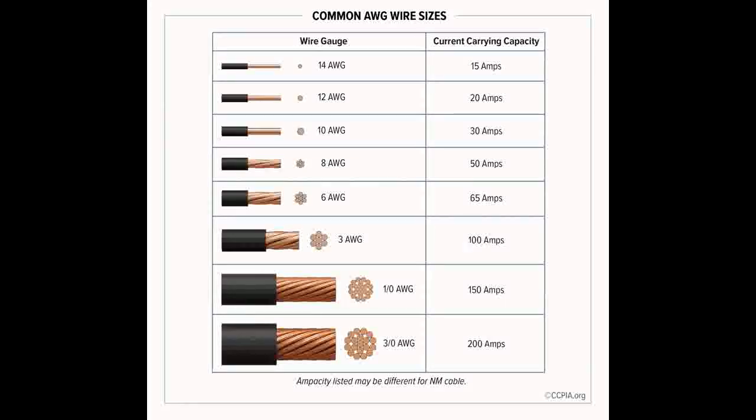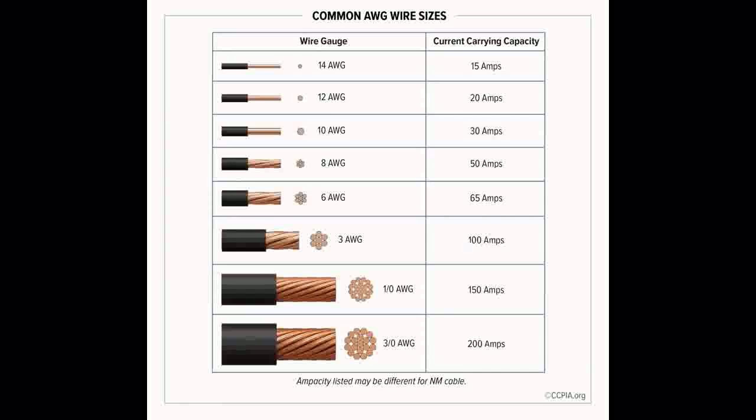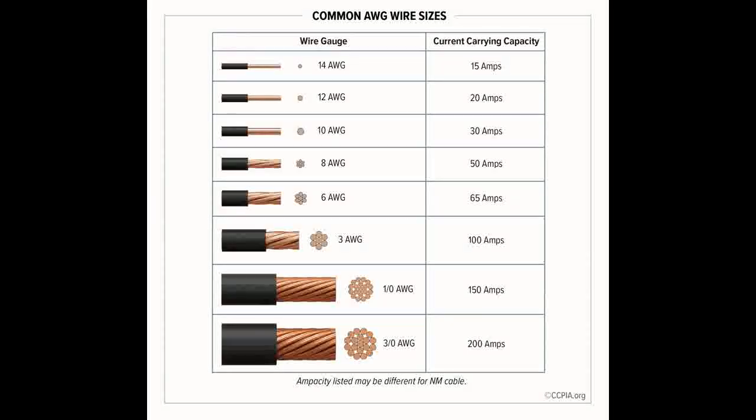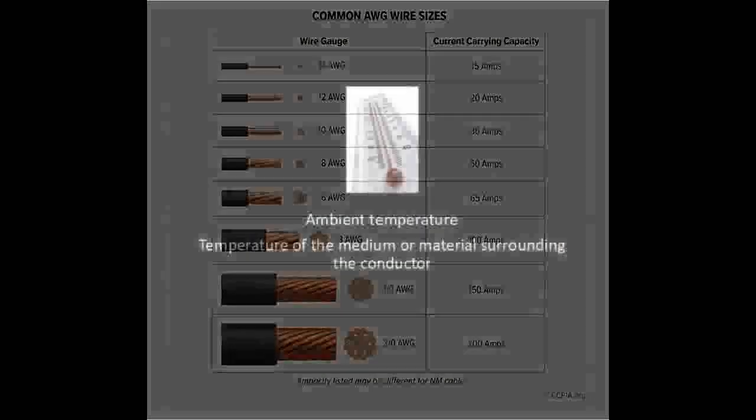This amount of voltage is undesirable and will no doubt cause equipment failure, especially for an electrical motor load such as a drill. A lesson in safety. When using extension cords to operate lights and tools, be sure that they have sufficient conductor size. The larger the wire size used, the smaller the voltage drop created. Small diameter extension cord conductors may heat up and burn. Motor-driven tools at the end of a long extension cord can heat up and operate inefficiently.